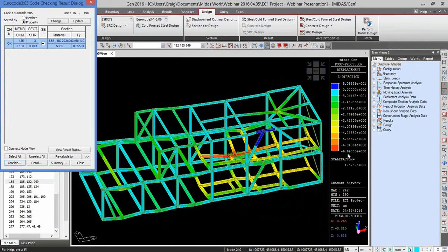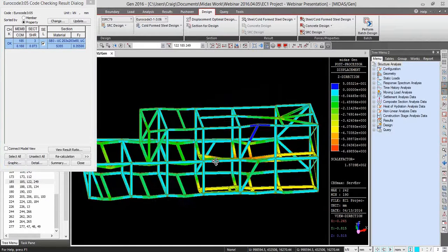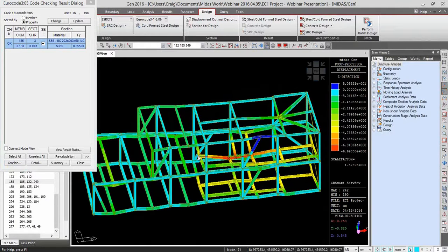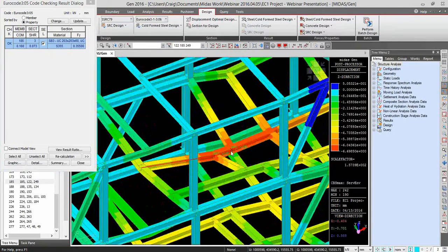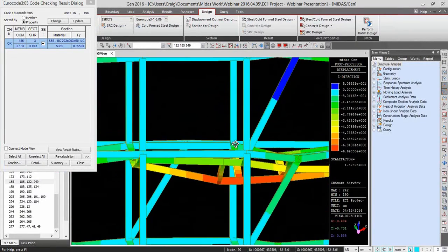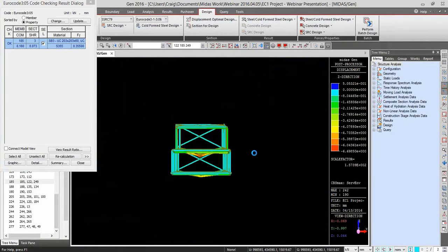However, the deflection limit here represents, we found it represents a compound deflection limit. So if you've got a deflection limit of -1 at this location, for example, and along the beam it's -5, it's going to show a deflection limit in the middle of -6, for example. So that's why that is displayed as that in this instance.